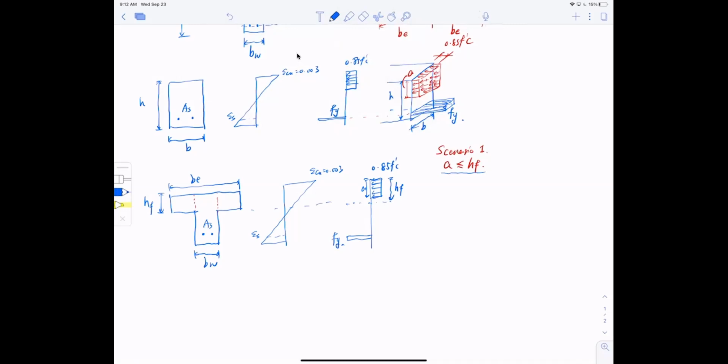All right. So JD, quick question here. Say if the compressive zone is within the flange, and I want to draw the 3D stress distribution. Will there be any difference for a T-beam or for a rectangular beam in that case? I'd say there'd probably be more reinforcement from compression in the T-beam, just because you have more concrete in the cross section right there.